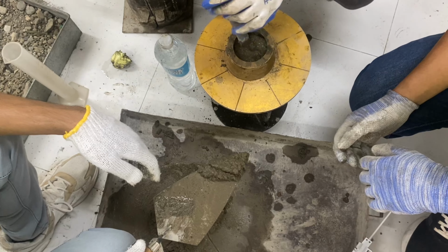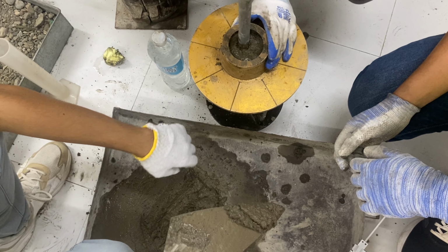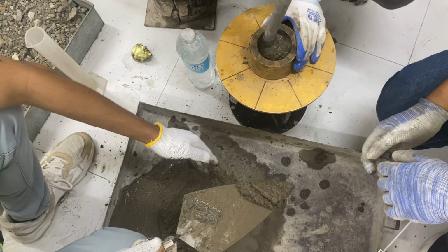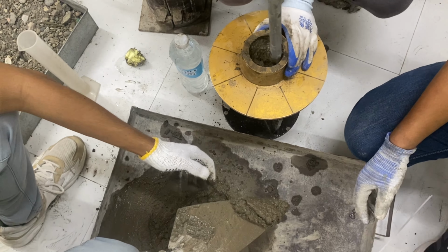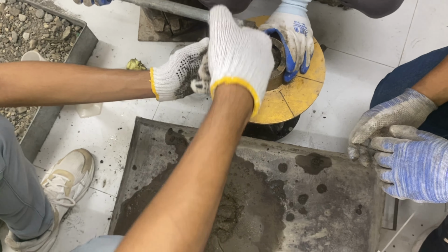Tamp the mortar layer 20 times with the tamper, applying just enough pressure to ensure even filling of the mold. Overfill the mold by approximately 20 mm with mortar and tamp it as specified for the first layer. Cut off excess mortar to create a flat surface flush with the top of the mold.